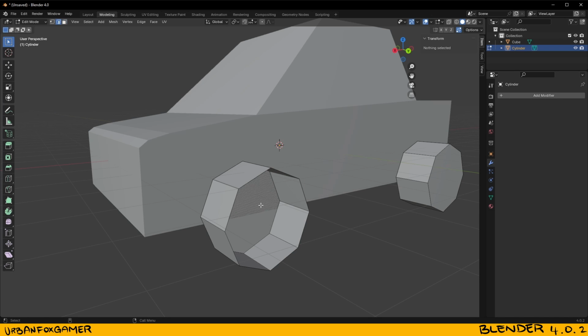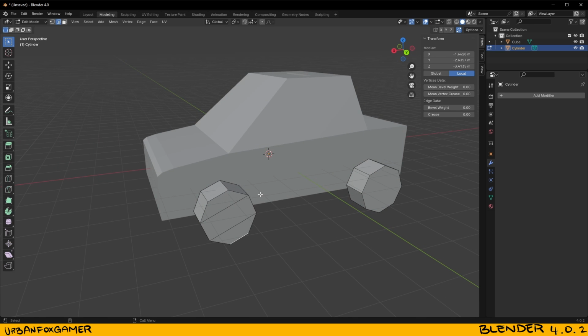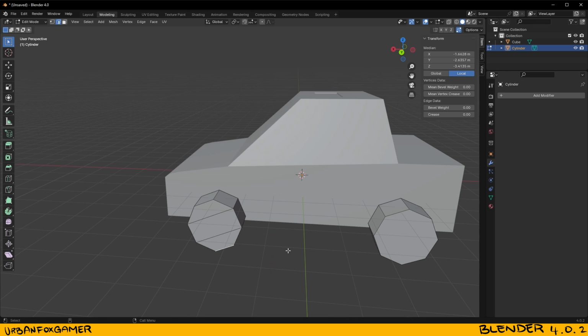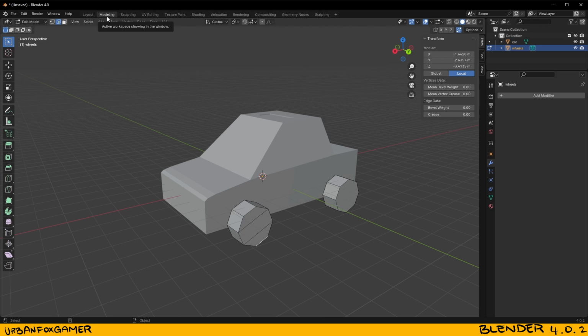Now I'm just going to press 2, click this one, press F, F again. So what happens there is it's creating a quad relatively close to where you pressed the first edge. It's very fast to build quads, but it needs some guidance. So technically, you have now created a car. By the way, there are other shortcut keys that I added because in the default industry compatible controls, they are not included, but these are the must-have shortcut keys that should be added in industry compatible controls.